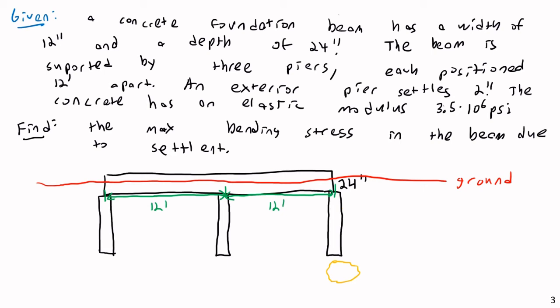If you take geotech, or you study foundation design, you will realize that there is always going to be some amount of settling present, and that's not a big deal, as long as the settlement is uniform. Because if you have a uniform settlement and the entire structure just moves downward, that can cause problems for things like pipes, water connections, electrical connections, data connections. If you have a pipe in the soil that comes out and connects to the building, and the building settles downward, that can maybe break a pipe or something. But in terms of the overall structural stability, that's not going to cause much issue.